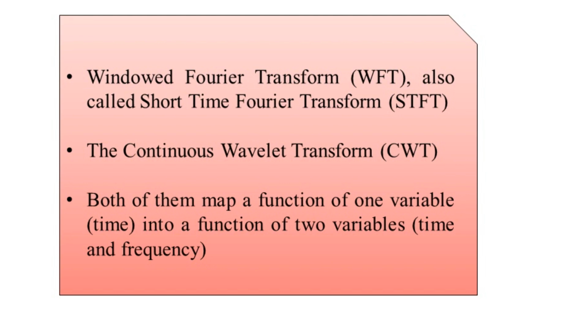This way the disadvantage of the conventional continuous Fourier tool is overcome by the use of either the windowed Fourier transform, also known as the short time Fourier transform, or the continuous wavelet transformation, and there are many more versions in the wavelet family. So this is what this particular topic was, continuous time frequency representation of signals.